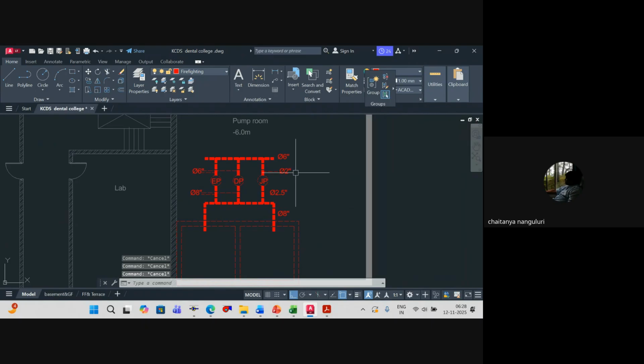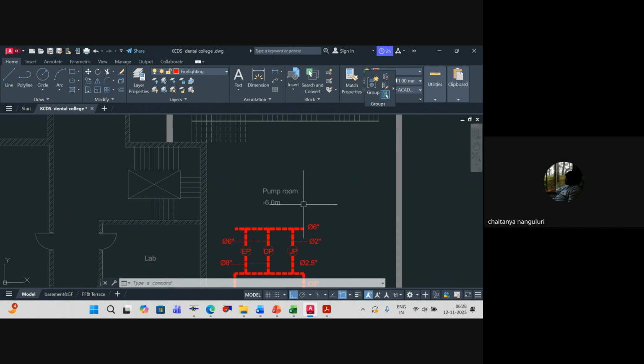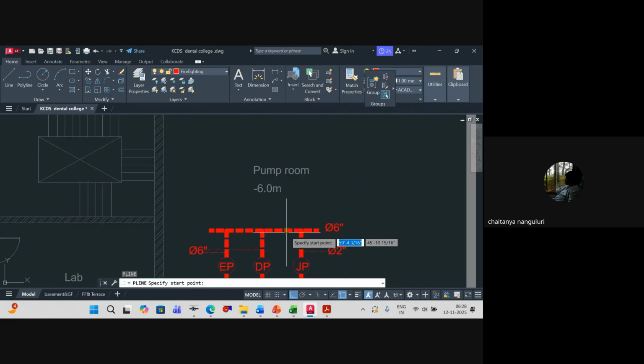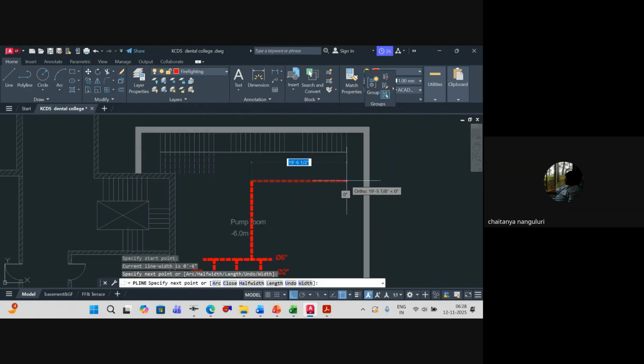Now we have to really worry about your common discharge manifold that will be connected. So when the discharge itself is 6 inches, you need not select higher than that. We can directly choose your 150 mm diameter pipe that will be coming out of it. Understood? Okay. So from here, we will choose your 150 mm diameter pipe that can come out through this element.